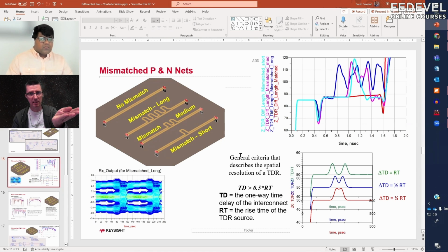So basically, just this impedance mismatch can close the eye. It's not even about the edges traveling together or something like this. This is just the impedance mismatch influence. And this is one way of seeing this impedance profile.